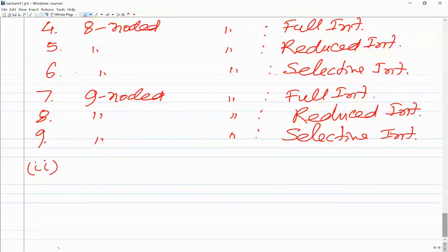So this is what I said, and this is the most popular technique. If you look at packages, for example Abaqus, in the element nomenclature at the end you will have R, and R stands for reduced integration. And when you solve a problem, you will also have parameters to control hourglassing, either a stiffness parameter or a damping parameter.